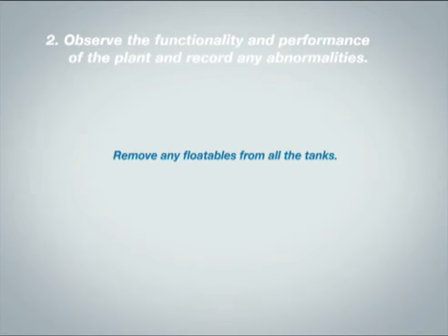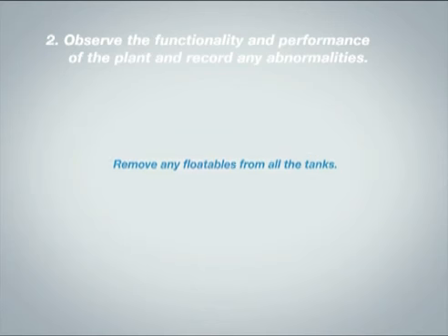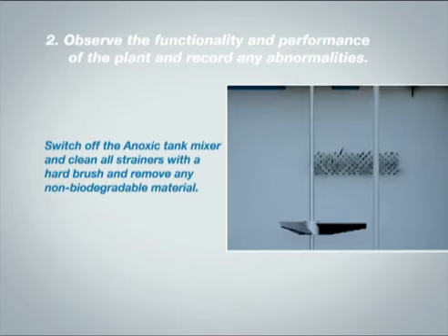Remove any floatables from all the tanks. Switch off the anoxic tank mixer and clean all strainers with a hard brush and remove any non-biodegradable material.